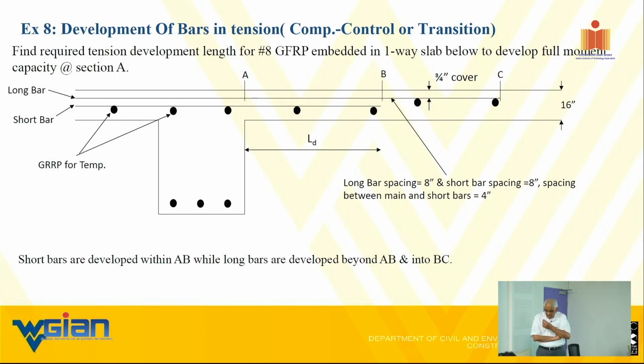I do not see people even in the US exclusively using sand coated. They are using either ribbed or a combined effect of sand plus ribbed. I actually put in the McKinley Wheel bridge both, the sand coated and the ribbed. Being a fairly big bridge, I had the luxury of putting both. I put half of this and half of the other. I actually put two different manufacturers' FRP rebars in there.